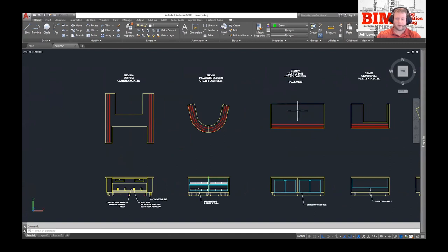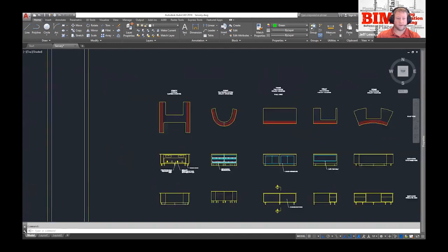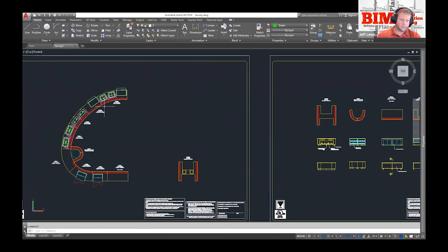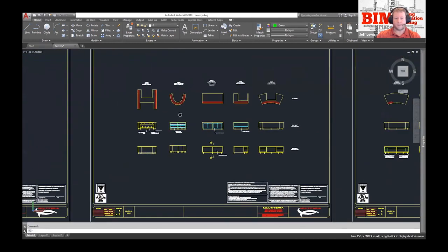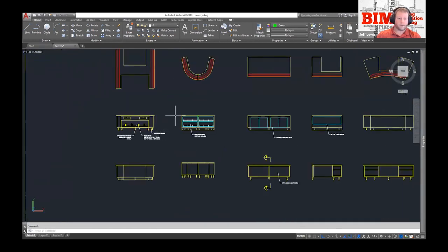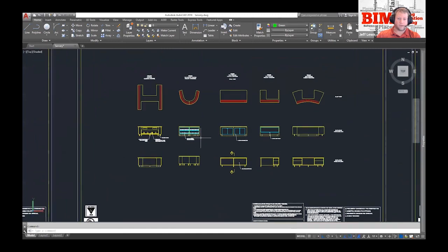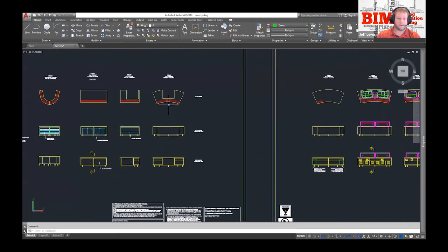As I mentioned, when building a REVIT family you would typically want to put the origin on the back left. But being we're building a curved piece of equipment, you really want to change your thought pattern before you even start drawing, and pick either the front left or the front right, because that's where the curve is going to be created. Even before starting any of the REVIT families, a plan of attack needs to be put in place.